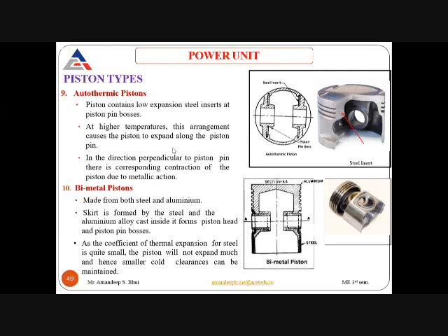Now at higher temperature, these inserts, because they have a low coefficient of thermal expansion, do not expand, and they restrict the expansion of the piston also. In the direction perpendicular to the piston pin, there is a corresponding contraction of the piston due to bimetallic action.